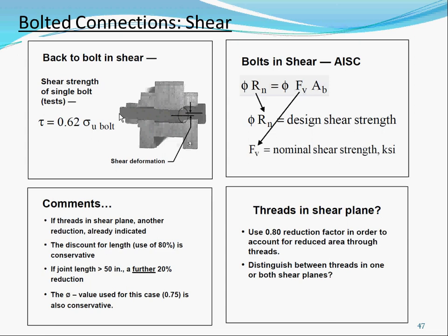So when you look at the shear capacity they publish, they have a thread condition N and then X. When you exclude the threads, you get higher capacity, whereas when not excluded, you get lower capacity, that's X threaded. And typically they say that's an 80% difference.